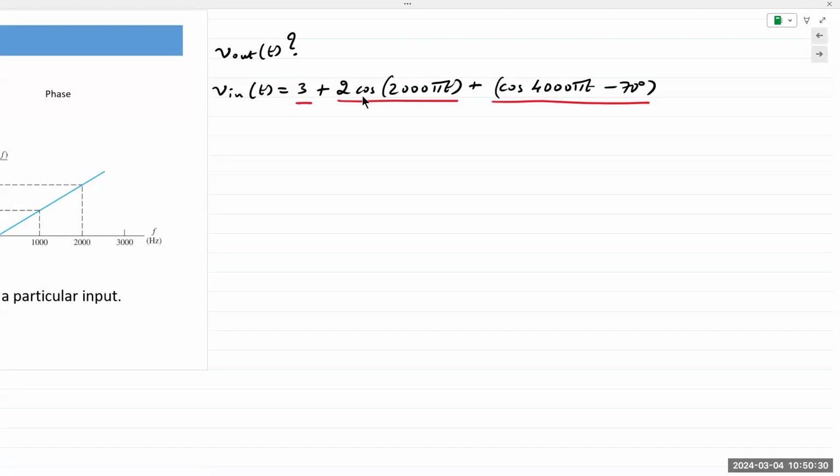If you're in a vehicle, sometimes if the line filtering is not good, you might hear the engine whirring noise coming out through the speakers. You may not have personally experienced this. I have, but you may have read about it, perhaps. That's the DC signal from the engine and the battery that's coming in through the speakers and interfering with the audio system. So there are filters in place to block out those components. And so this could be something like that. There is a DC component in the signal.